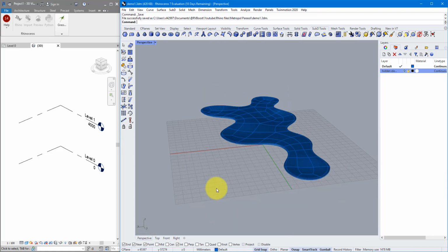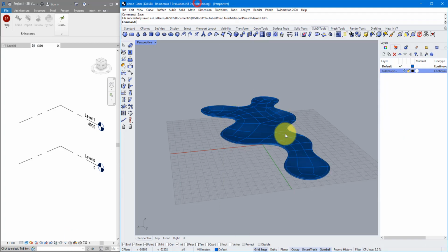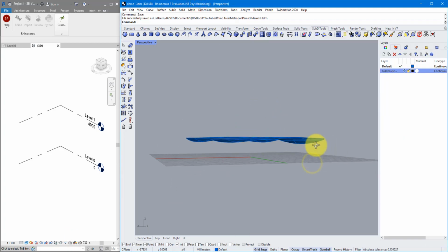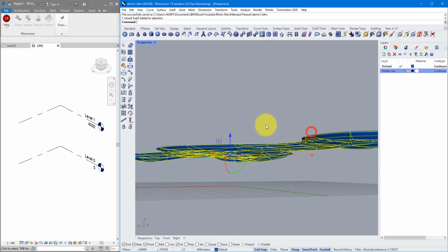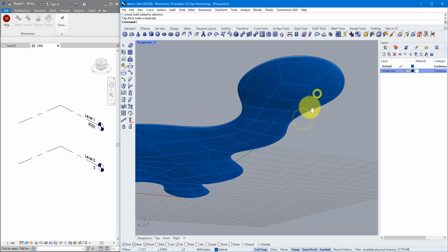Moving on, it's time to create these very attractive columns. And here that's where I can take a look at the bottom of my form. Maybe even move it a bit up there. And now I can select again with Ctrl Shift this bottom surface there in the center of this circular region. With that selected, I can extrude it down to create our column.